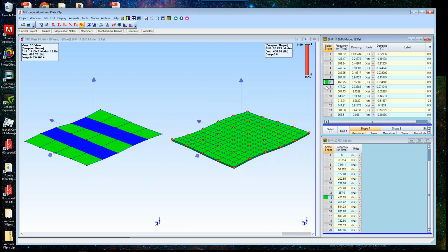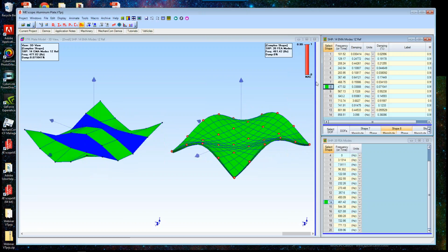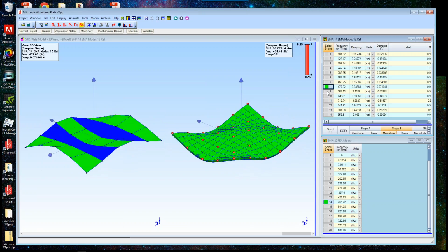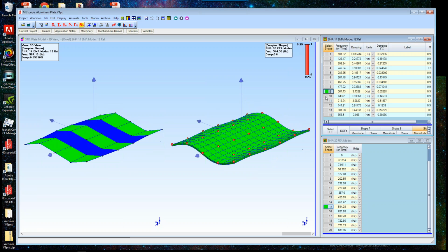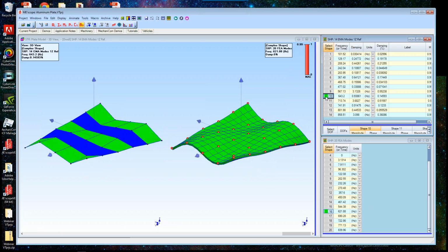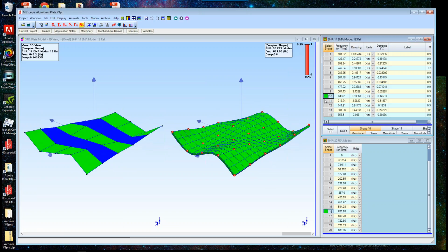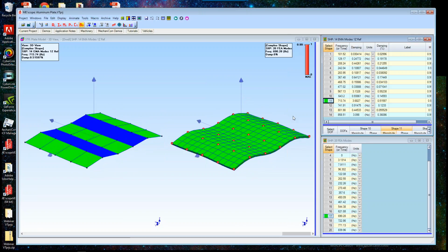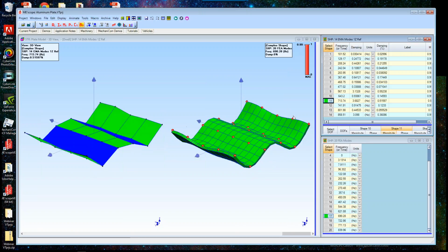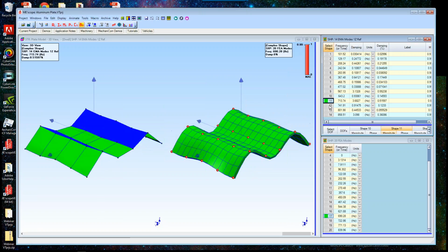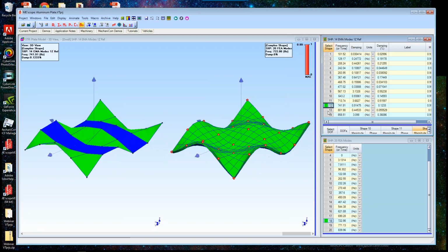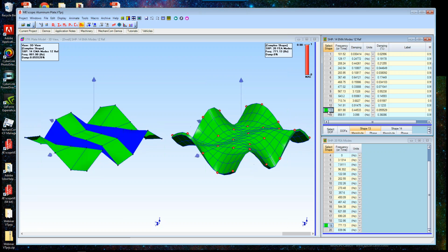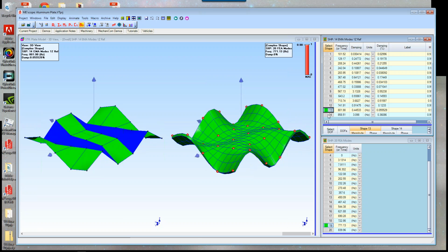So the software takes care of all that for you, provided that you've numbered your points properly on the FEA model. Again, that's why we call it an experimental FEA option, because we want to purposely make the FEA model match up with the experimental model so we can compare answers when we're all done. So you can see of the 14 shapes, it has almost perfect correlation, 99%, here's 98%, between the experimental and the analytical data.